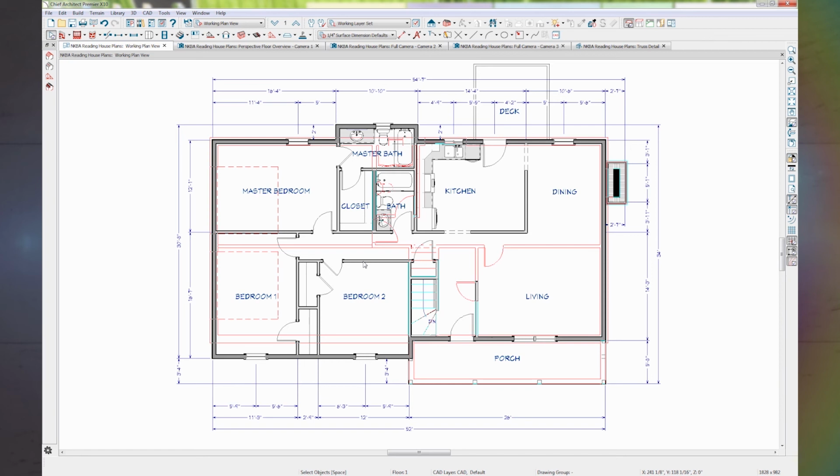Is it possible that the ceiling and the roof could be supported in a manner other than interior load-bearing walls or beams? The clue can be found in the original plan. Let's take a close look at that information noted in the master bedroom. There's a little note with some very valuable information, such as prefab trusses will be used, and an arrow that indicates their direction from the front of the house to the rear of the house.